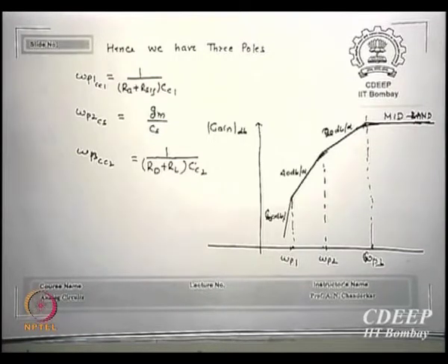Phase, but somehow you are assuming stable, phase is less than 180. Yeah, you are perfect. Phase margin as it is called. But what else? There is another term which is worrying us, which we never so far calculated. In every system, that first we must calculate. What is that? Power. The most worrisome part in all of this, at the end of the way we find, it is the power dissipation which will limit everything.